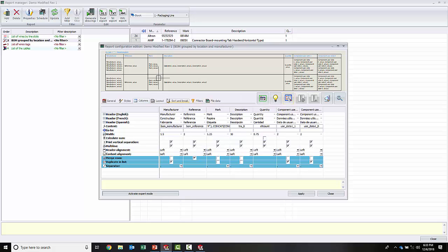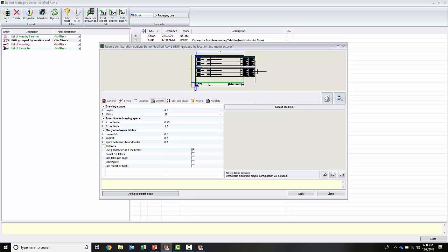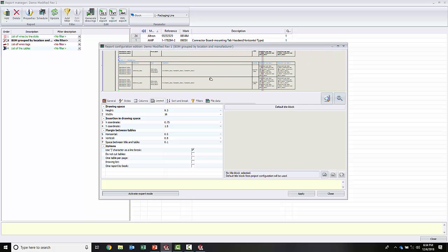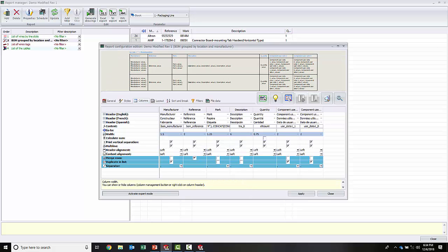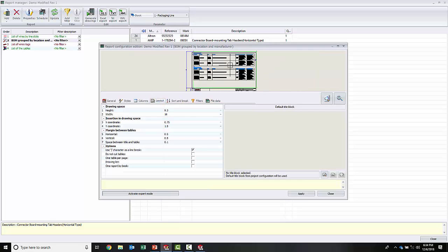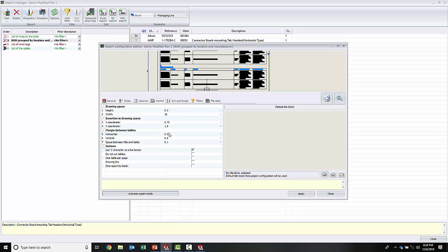By looking at this, you can then go into the layout to actually see what this looks like. And oh my gosh, look at that. My layout is a little bit bigger than my sheet. I don't want that. So I'm going to come back in here and make a change to this description by the 4 inches that I added. By making that 6 inches, it's going to drop it down. Of course this works the same way up here at the top, where you can see that in this layout. The layout shows you what you actually have, and you determine those numbers.